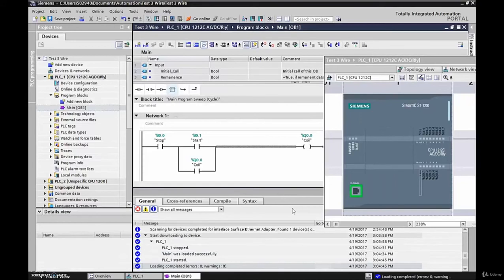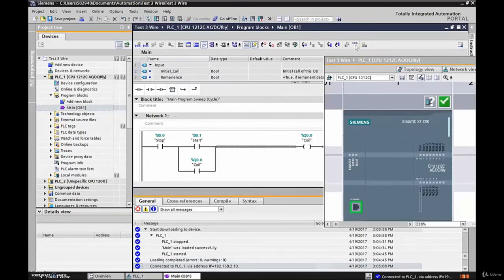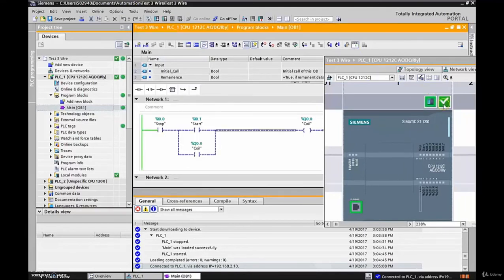There we go. And similar to the Allen Bradley, this guy doesn't go live right away. So in order to view exactly what's going on with the PLC, because we don't see any green lines anywhere saying that we're actually talking to it, let's come over here and we're going to find monitors. So monitoring on and off. We're going to left click on that guy. There we go. So now we've got a green check mark here. We are talking to this guy, and we're connected into the PLC, and you can see that this is connected into the stop push button.